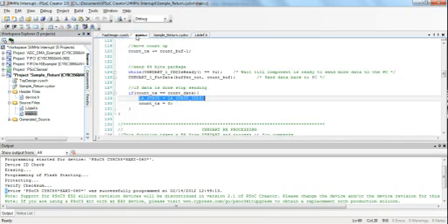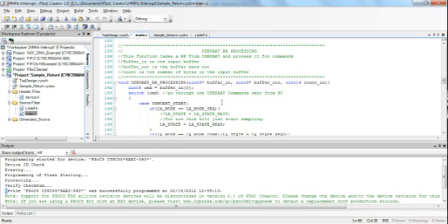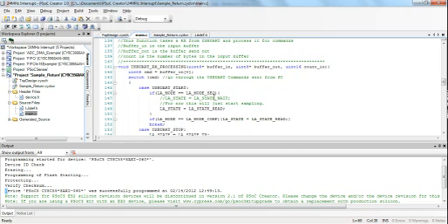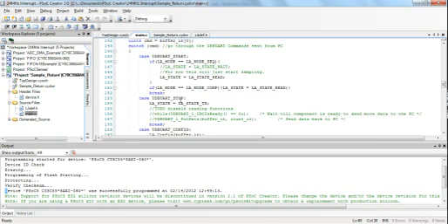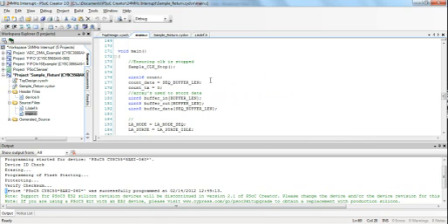Back to the main code. This is the receive processing. It happens whenever a receive packet is received from the host computer. It breaks out in a case for USB start, stop, and config, and what it does. Looking down, the sample clock is turned off just as a safety measure.